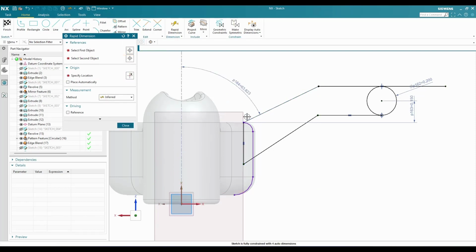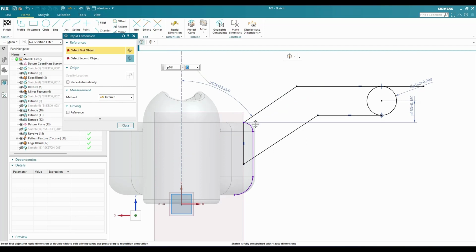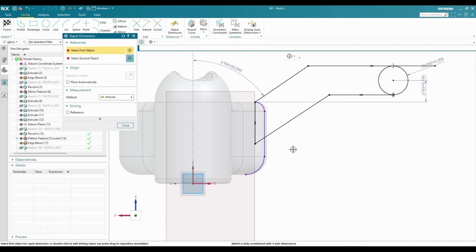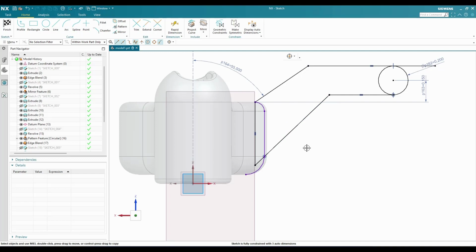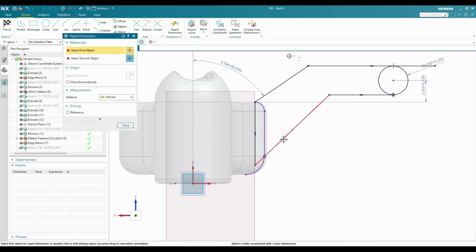It is 55 degrees, and I'm going to make it a point on a curve. So press C. This point should be on this curve. Now there will be an angle here. Press D, and between these two there should be an angle of 12 degrees.